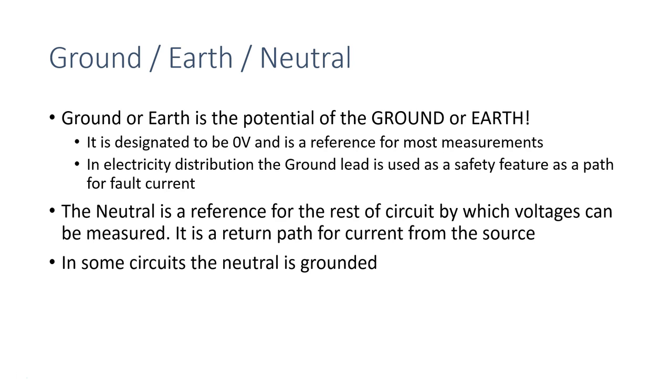Now when we talk about ground or earth, it is the potential of the actual ground or earth, the earth that you stand on. And we designate this to be 0 volts. And this is a reference point for measurements, especially in the power system. So if you go to a substation, say, you will see that the measurements are taken from the transmission line or from the bus to the actual earth, the ground. So that is for a power system.